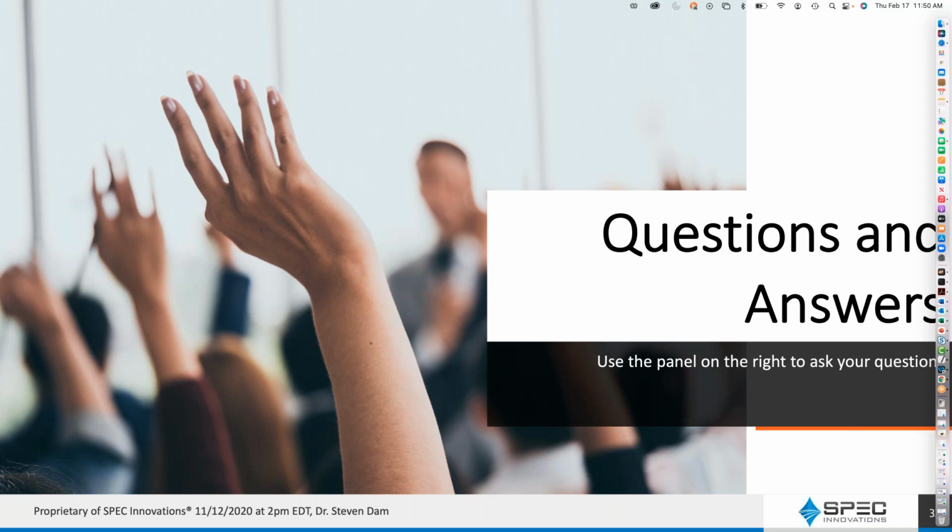Our next question is, can you link to or get requirements from Rational DOORS? Yes, actually we have ReqIF import-export capabilities, so you can use that as a mechanism. There's also a good CSV import-export, which can do that too if you're not used to ReqIF. I highly recommend ReqIF as the more standard approach. Also, DOORS Next Gen is a cloud-based tool, so you can create hyperlinks between the two very easily, and I've done that in the past if you need to.